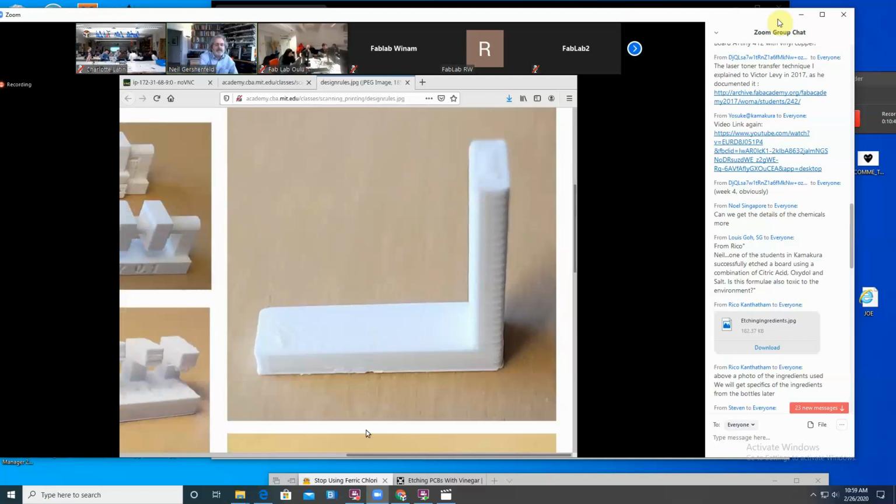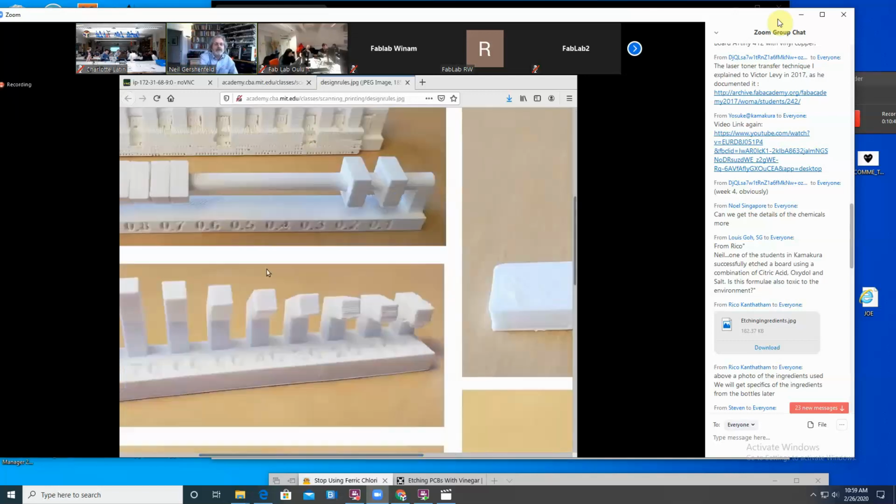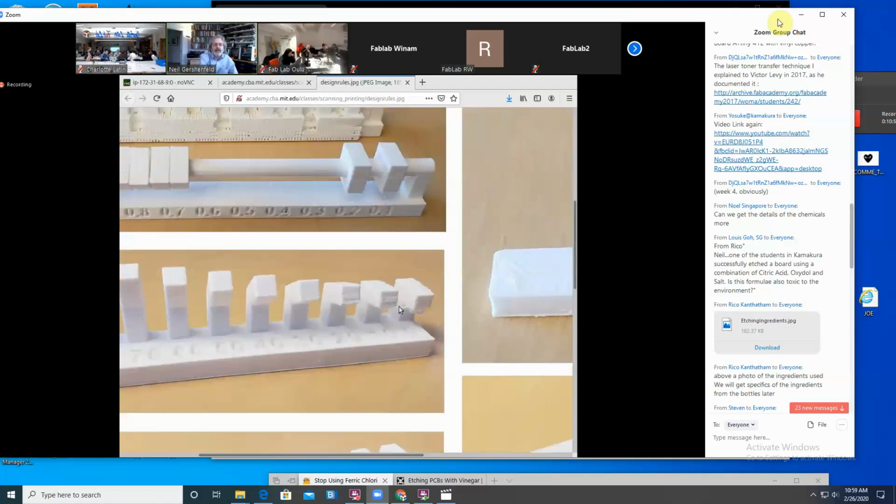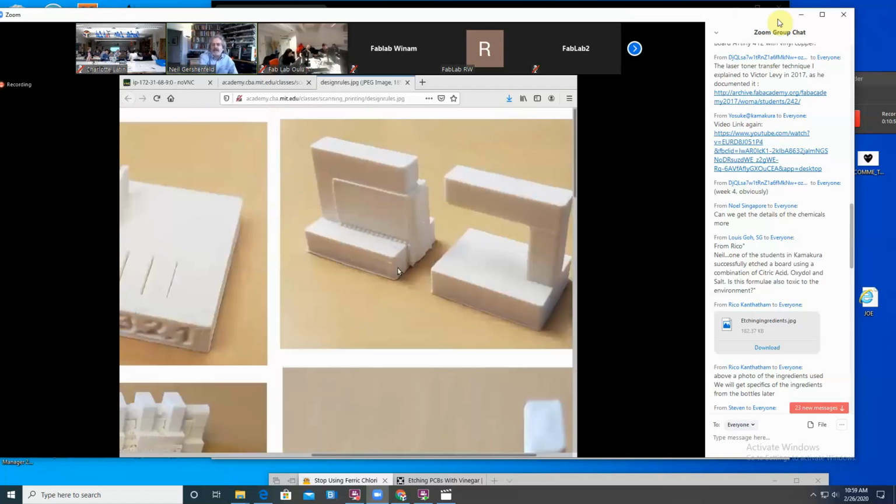As much as possible, it's a great idea to avoid supports. And so as long as you're bridging, or as long as the angle has enough of an angle, you can design around not needing supports.